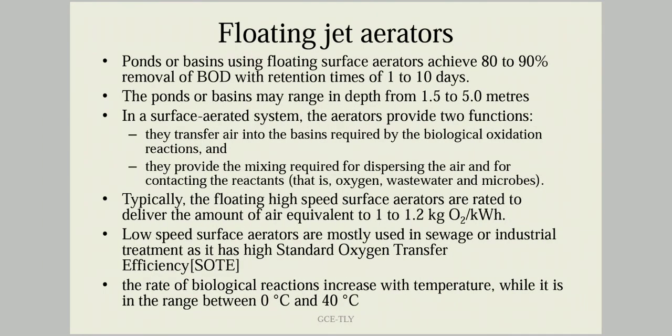So, floating jet aerators. The ponds or basins using floating surface aerators achieve about 80 to 90% BOD removal, and have a retention time of 1 to 10 days. The depth of the pond may vary from 1.5 to 5 meters. In a surface aerated system, these floating aerators provide two functions.